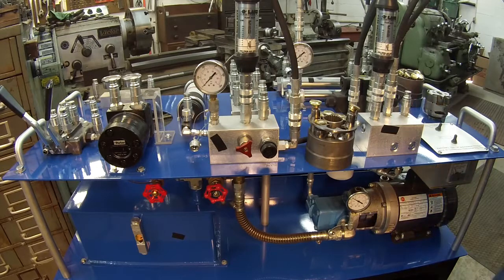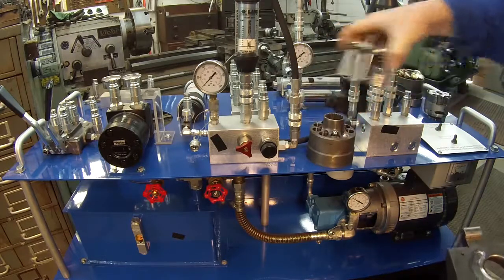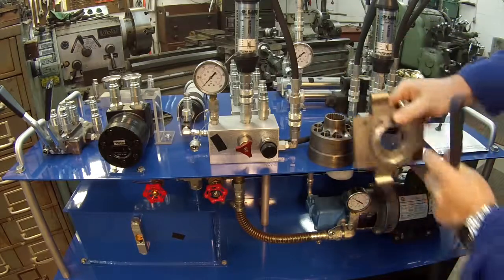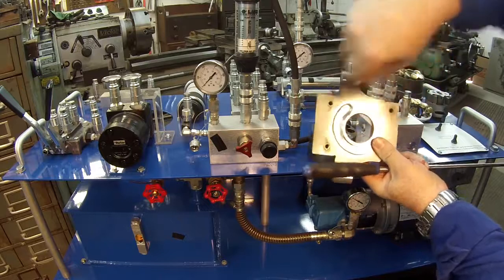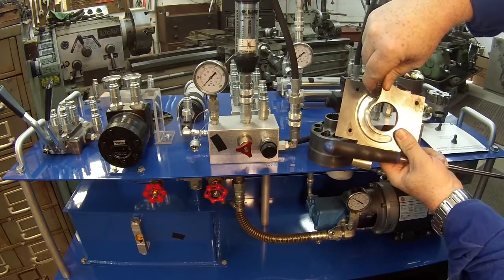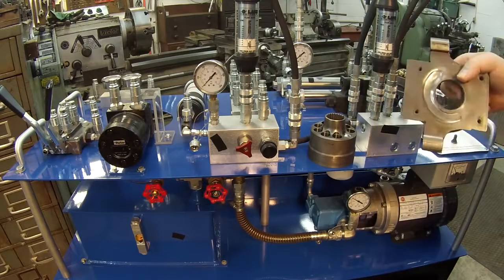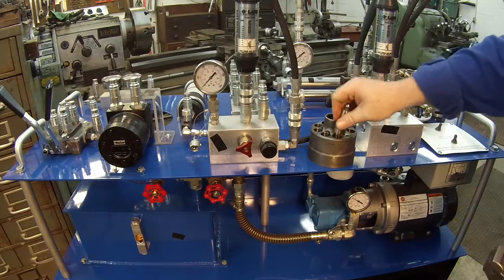Alright, so when those pieces come apart like that, this piston right here, the shoe came off and actually dug into this plate right here as it was spinning around on here, and that's the reason that it finally failed. Okay, so it's important to understand what cavitation, aeration, and those things do to your system. Very, very damaging to your system.